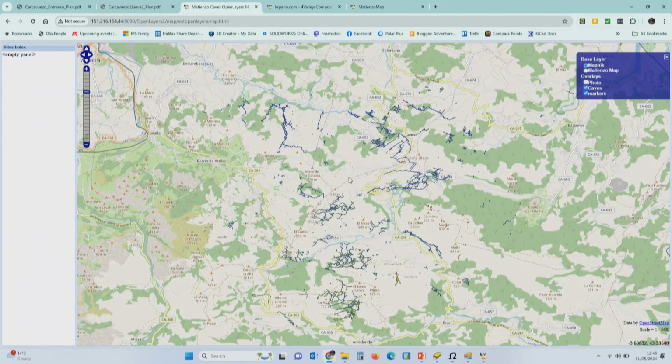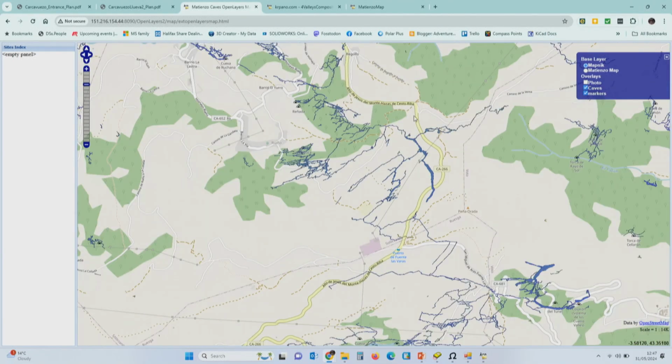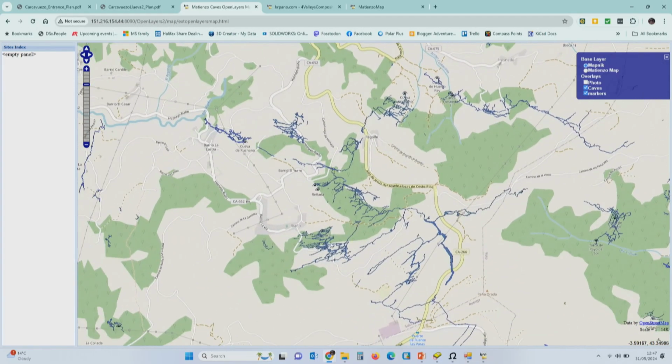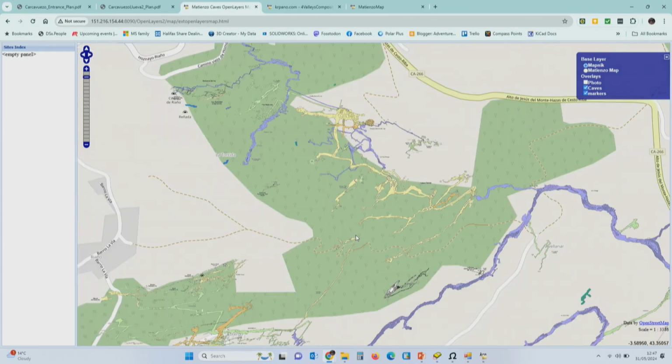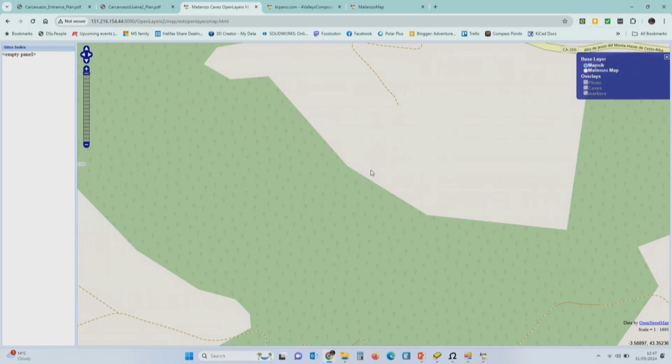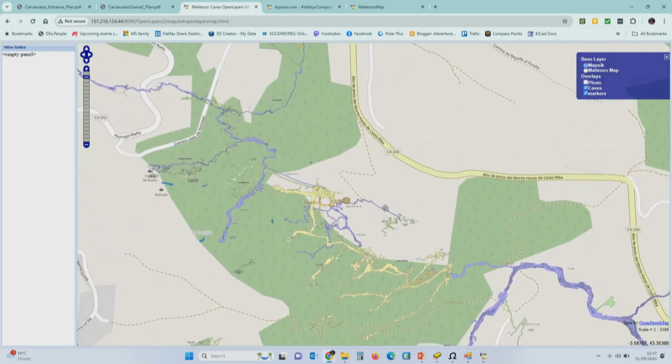Some other ways we've come up with for presenting a 70-kilometre cave system map? That's a big sheet of paper. It's impractical to print them out. So one of the things that we've done is produce these map overlay tiles. This is the cave system we were looking at in northern Spain, and you can see that as I zoom in, the cave survey is overlaid, initially as the 3D model, and then as we zoom in further, we actually get down to the detail.